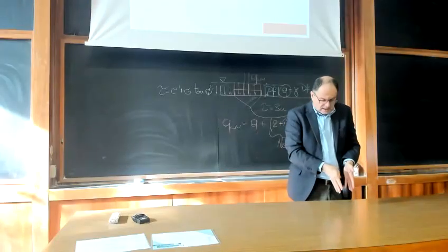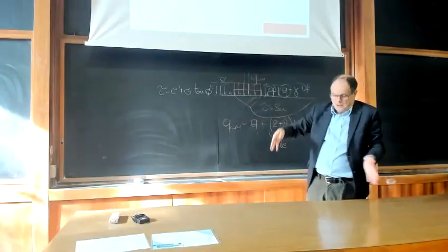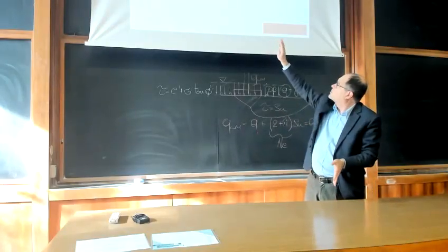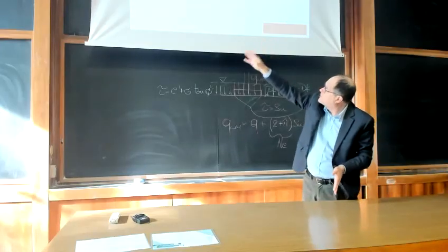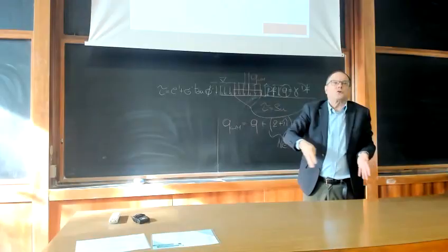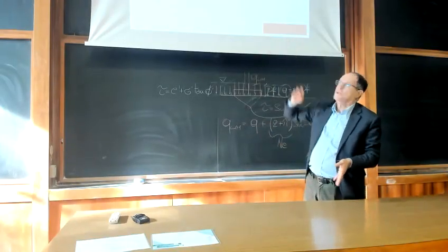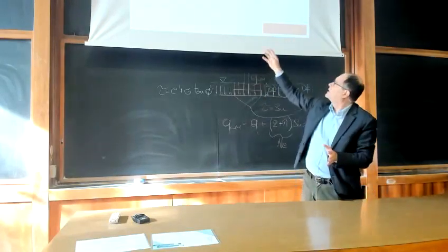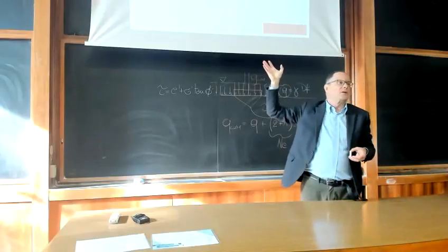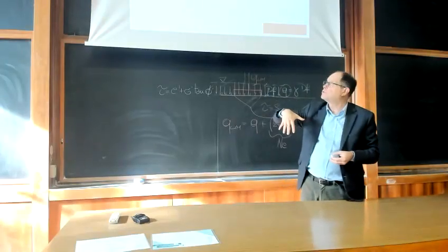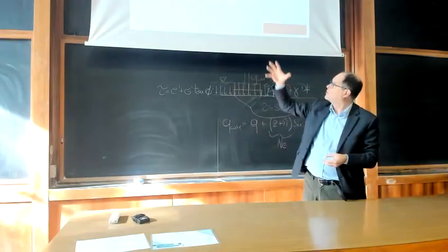Now, if the soil is expanding laterally below the foundation, it will compress the soil at the side of your foundation. So if from this side you have an expansion of the soil, getting to an active condition, on the other side you have a compression of the soil, getting to a passive zone. So this is consistent with the mechanism we have just introduced and with what we said yesterday about the Rankine zones.